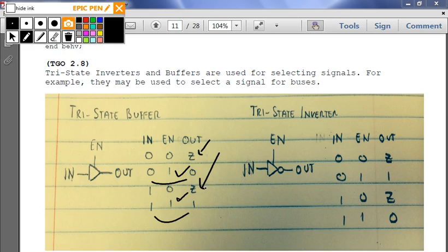The ALU calculation for the address is going to take a lot longer than just the value you're getting from the register, which means you need to insert buffers to hold the value coming from the registers until you've successfully calculated the address, at which point you can put them both into memory. So this is an example of when you want to use this.